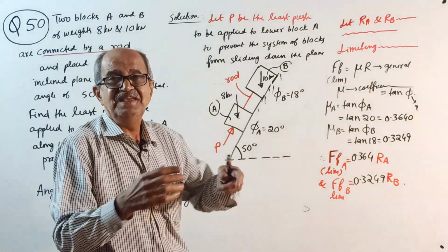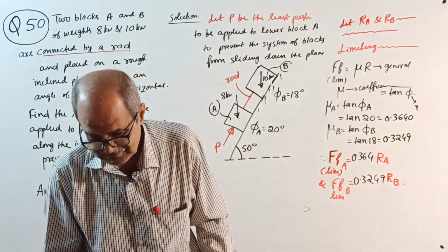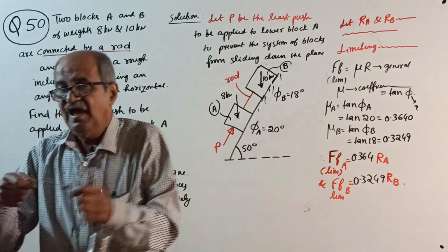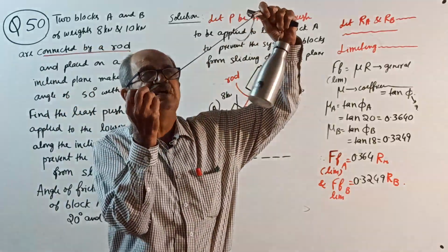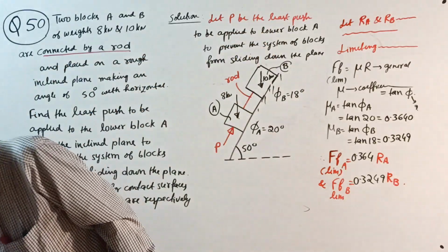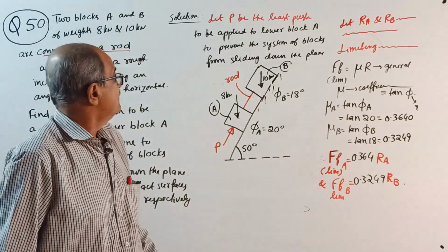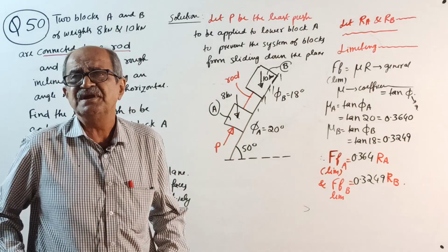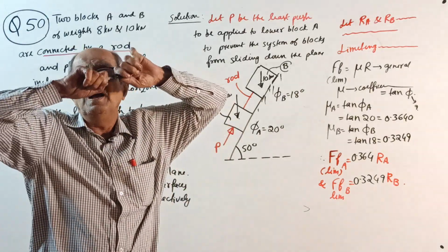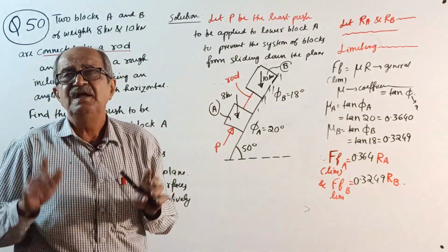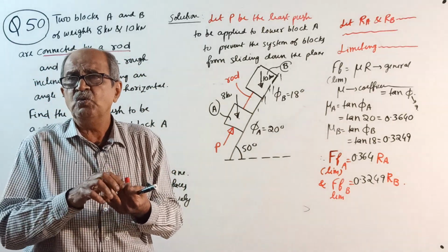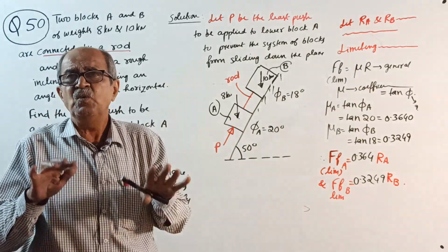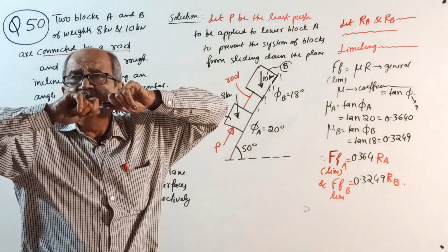Cable will fold. See there. I already showed it earlier. The cable will not stand. See? As you apply a push, the cable will fold. So that is why they are giving a cable. See, when a rod is given, it can take either tension or compression. Anything will do. This I told you. But cable, or rope, or wire, or string means it should be a flexible member. It can resist only tension.